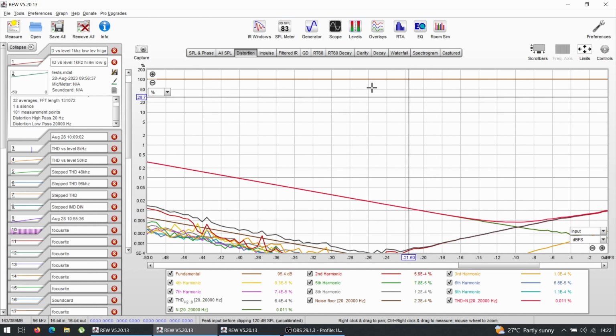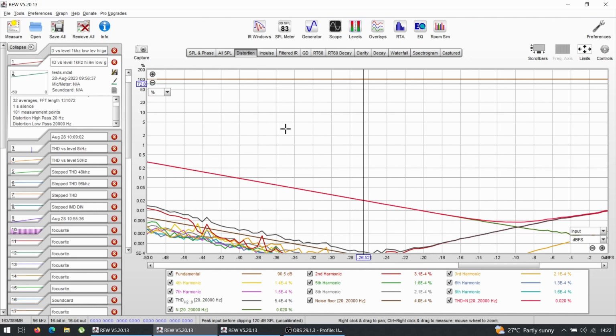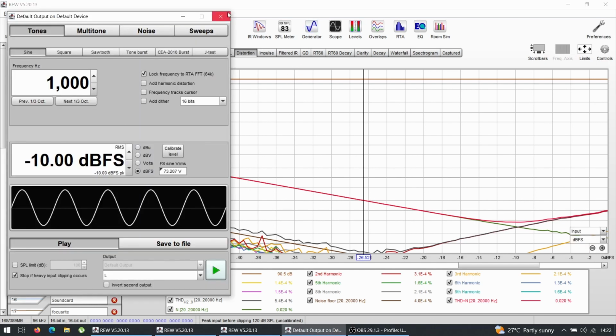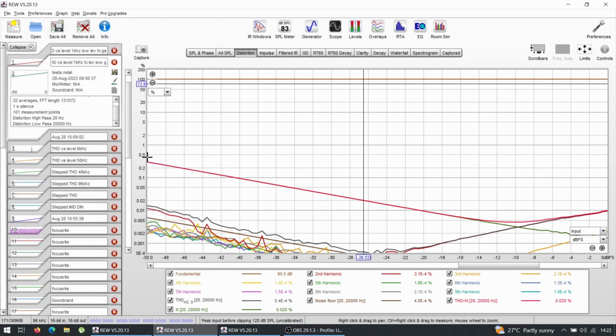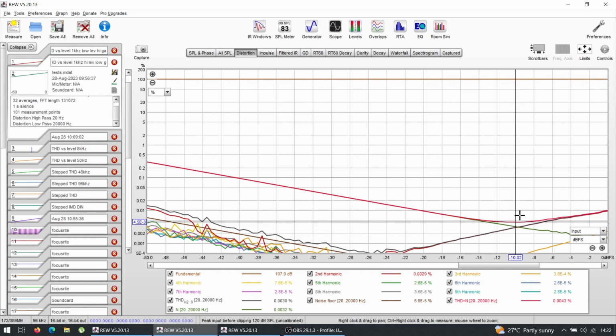And this particular measurement is the audio interface itself, how it's THD versus level. So the THD of the audio interface depending on the level of the signal. And I told you that I will come back to that -10 dB, because when you do a sweep, the audio interface THD goes down, down, down. It's the lowest at about -10 dB. And then if you bump the signal up to 0 dBFS, it goes up. Now it goes up from 0.05 up to 0.1. So it's literally nothing.